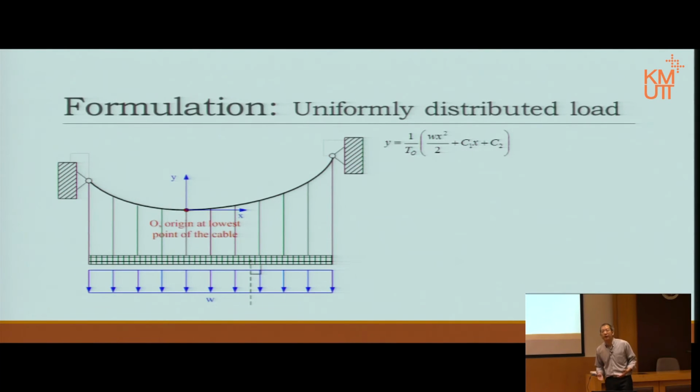We discussed this before, so let's not go into detail, but that is something we have been talking about since the first half of this course, when we drew the graph of the bending moment diagram and shear force diagram. So that is why we set it there, because we have two conditions. One, the xy coordinate is x 0, y 0, and two, the slope is 0 at x 0, y 0.